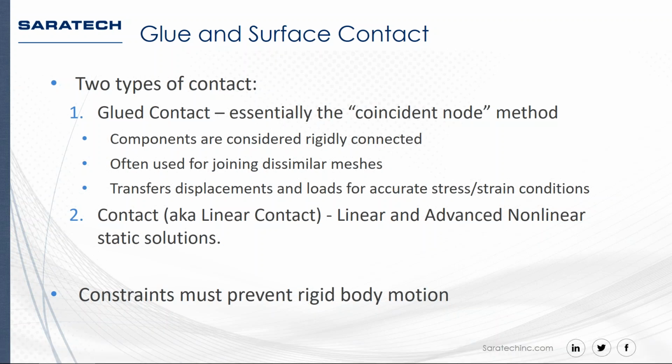Now, as with any linear solution, you do need to be mindful of the constraints. You want to make sure the model is properly constrained so you don't have any rigid body motion, so parts aren't just flying off into space.